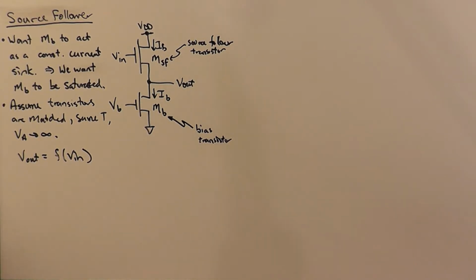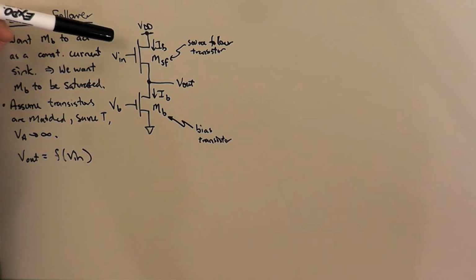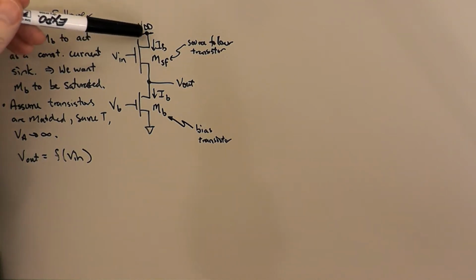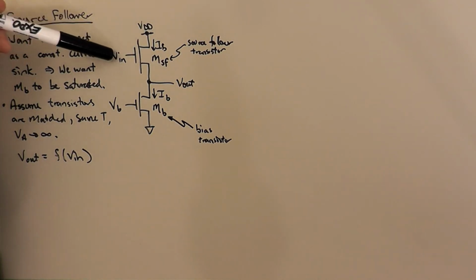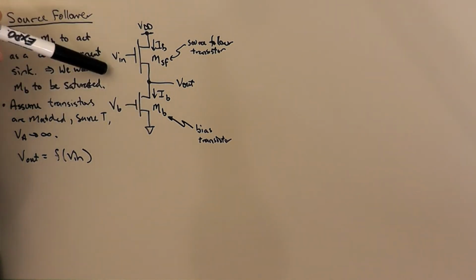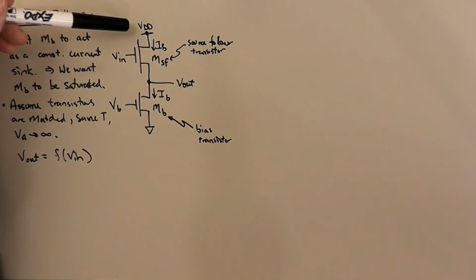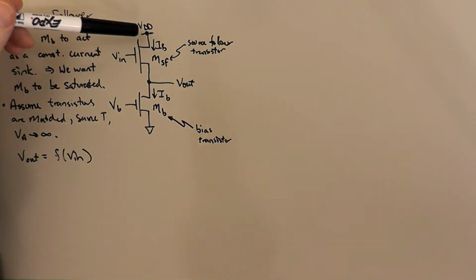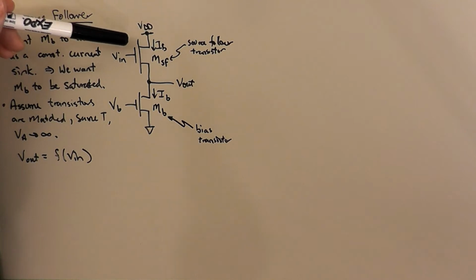If you remember back to our discussion of the emitter follower, the emitter follower, under worst case conditions, was diode connected with respect to being in the forward active mode. If we assume that the input voltage is only strictly within the range of the power supply rails, so that Vin can be at most the positive power supply rail, when it's up at that highest value, then the transistor's base voltage was equal to its collector voltage, and it was basically diode connected.